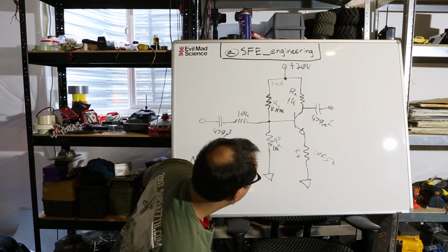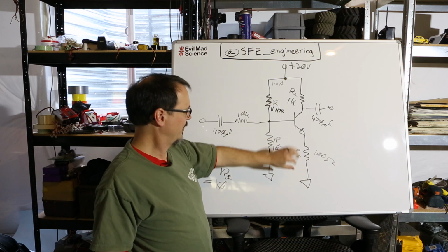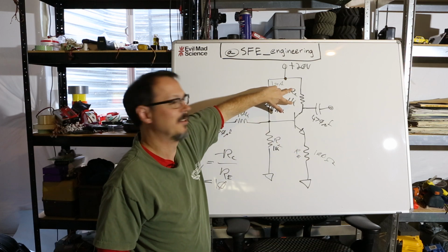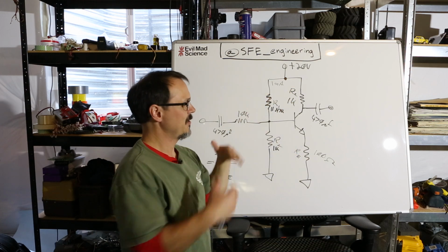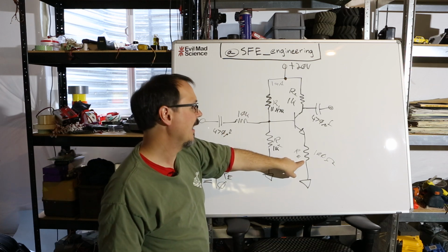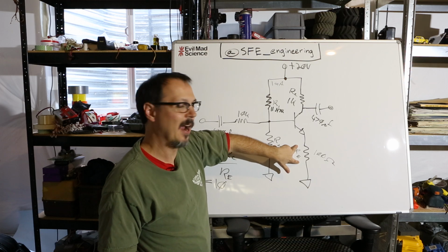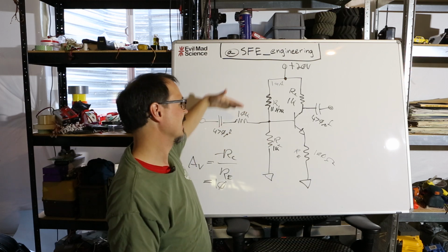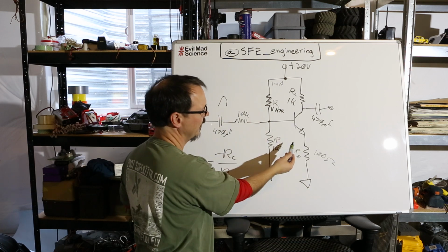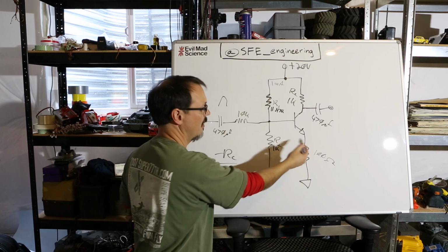Why is that? Well, it kind of makes sense if you look at it, right? If you're turning this thing on and you've got like 1 volt increase over that 100 ohm, you're going to have a 10 volt increase over that guy, okay? So you can kind of see that's how your voltages are going to fall. In the example I just gave, the voltage is increasing on that guy as I'm driving this up, right? So I have my high going signal here. It's turning this on more. It's creating a larger voltage across RE, okay?